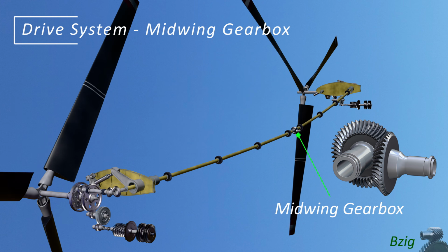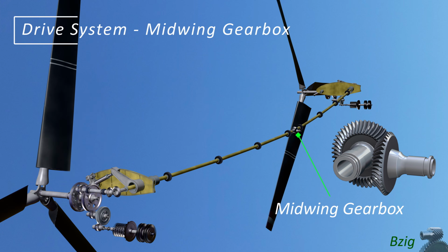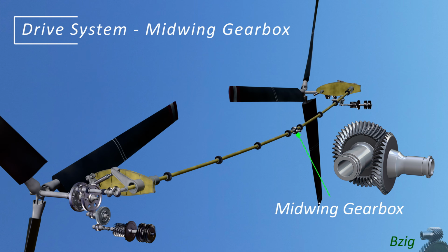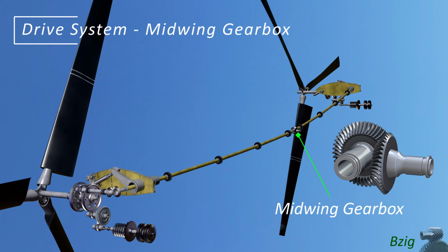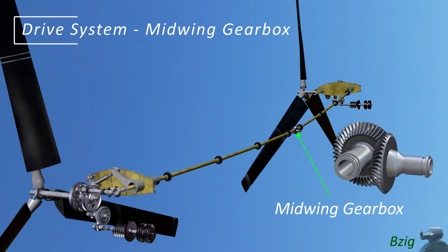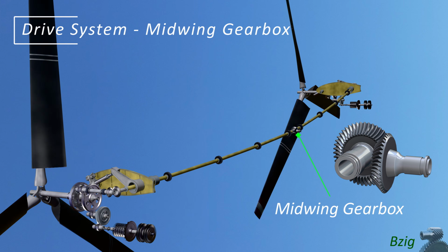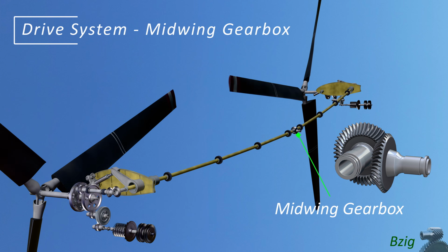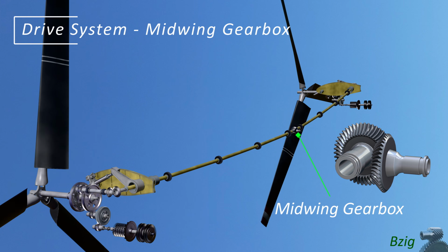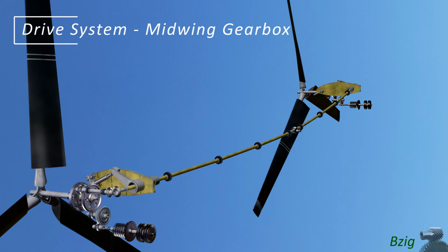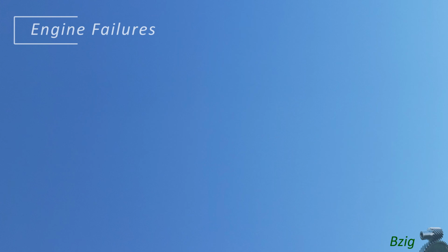And unlike most transport airplanes, most tilt rotors do not use engine accessory drive for hydraulics and electrics. Instead, these are usually powered from the rotor drive system. Other airplanes use things like ram air turbines and auxiliary power units to provide this power during all-engine-out flight. But this isn't necessary in tilt rotors because the rotor drive system always rotates. It's always capable of powering those subsystems.